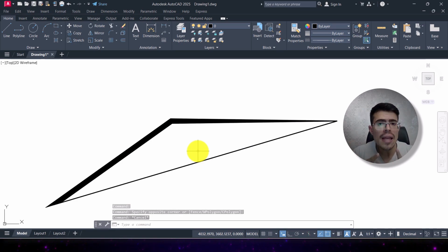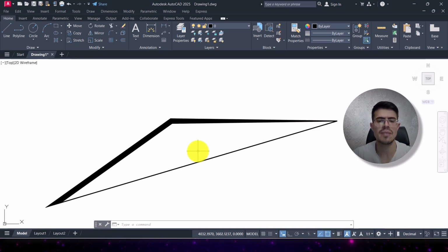It was all about the polyline, but polyline is not finished yet, because I promised you that in our future tutorial we will learn about its subcommands, which are arc and length. But as I promised you, what is the difference between line and polyline? One of them was this: you can draw with a different line width. The other one, which is really important, is this point.